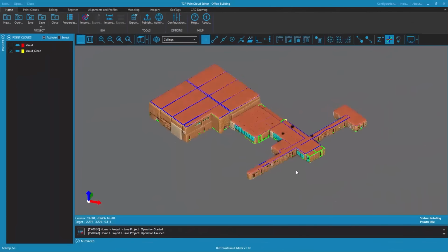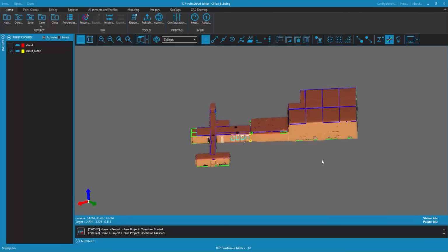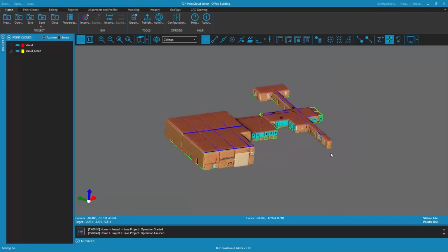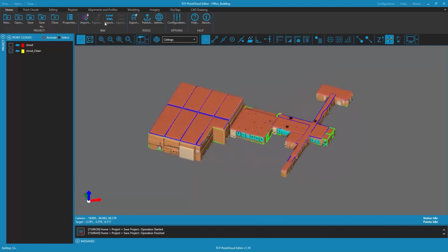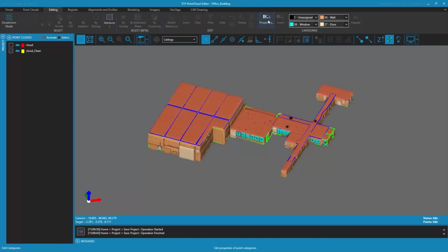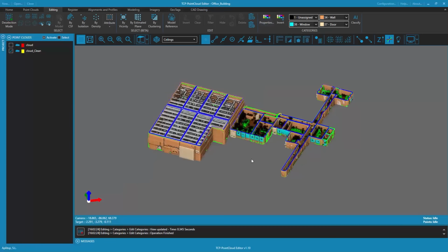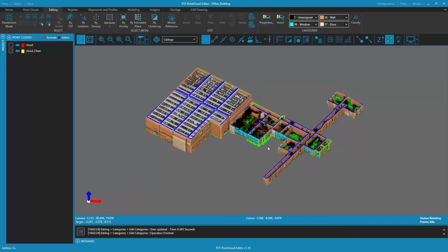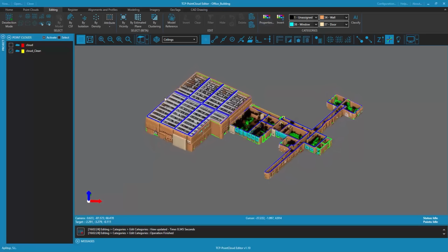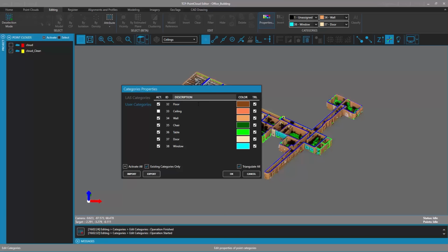Using all the tools seen above, we modeled all elements of the building structure, such as floors, walls, windows, ceilings, and doors. By hiding the points in the ceiling category, the interior of the building is better appreciated. By hiding different categories of points, you can check whether the features in certain layers correspond to the points in the point cloud.